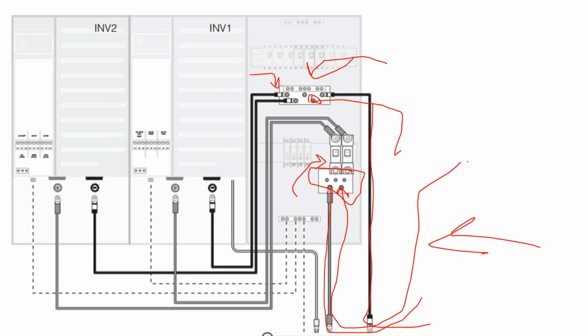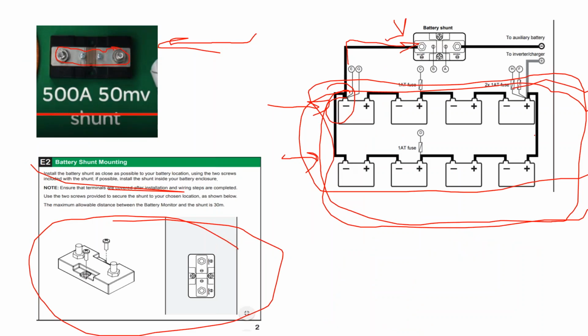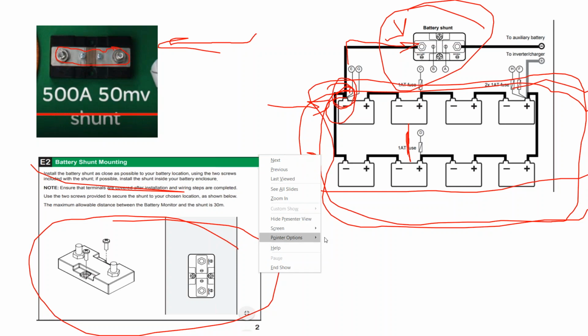And my field electrician was telling me, well, I don't know where to land the shunt. And I'm telling him, well, look, it's in the manual. We have 2 strings of batteries and 1 shunt. We don't need 2 shunts. It should be able to be landed on it. But he says, well, look, we're not paralleling our strings at the battery itself.